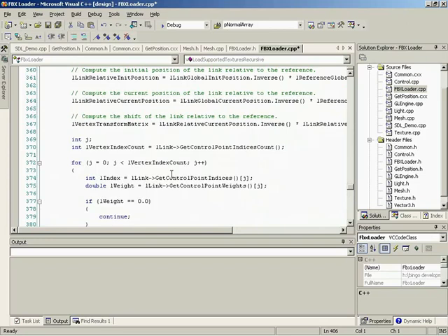Yeah, so to sum it up, compute transformation calculates the amount of transformation necessary to modify each vertex, by going through and looking at the animation on all the links or all the skeleton joints, and then using that along with the weights, doing all of our different multiplications to calculate the new position of the vertices. Exactly. And this is going to be called, again, from the last lesson, for every single frame. Exactly. We're baking this out.